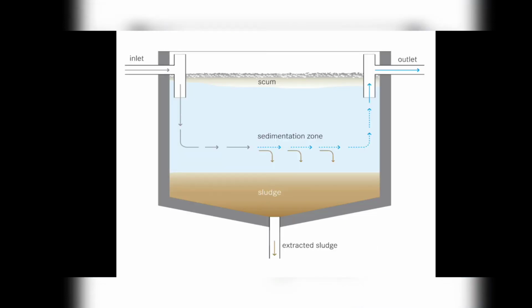Sedimentation and clarification: once the flocculation process is complete, the water then passes over the weir in the flocculator and travels to the center of the clarifier or sedimentation basin. Here the water makes its way from the center of the clarifier to the weir at the perimeter of the unit.